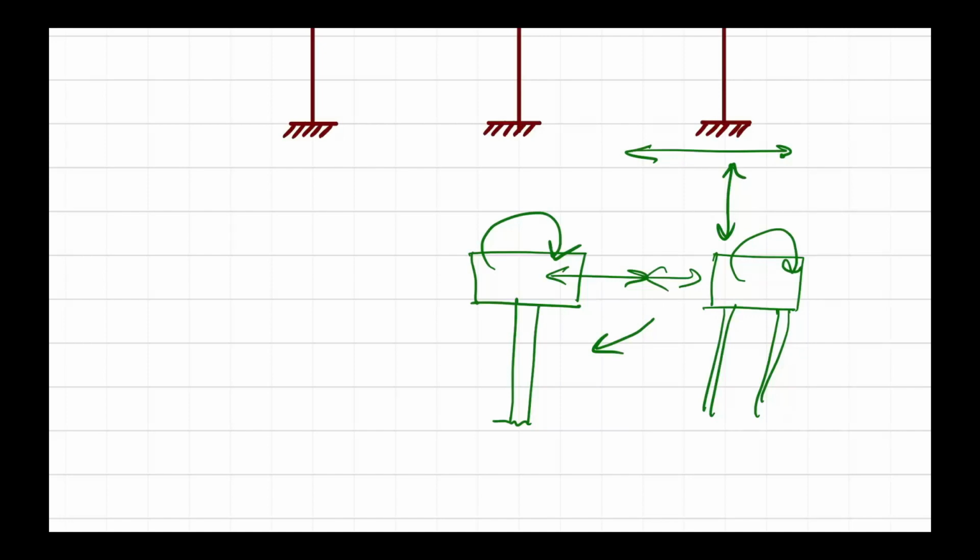Why do we put F2? Waste of money. So we put F1. When we put F1, then the pile head fixity seems to be out of our knowledge. We cannot guesstimate the horizontal stiffness of the foundation. We cannot gauge the rotational stiffness of the foundation. And then we assume the fixed condition. So now, how to come up with that perfect fixity?